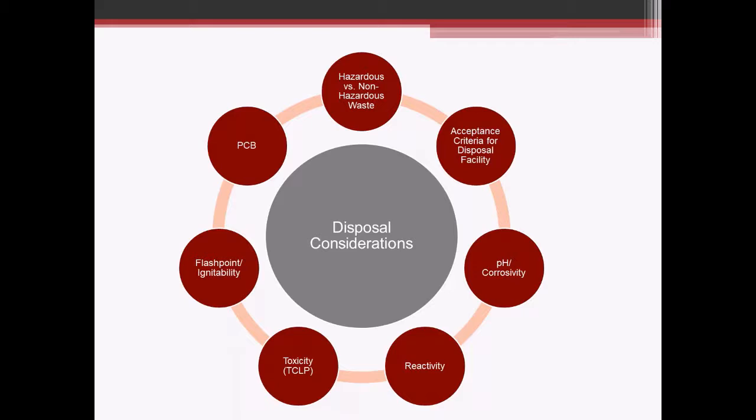On the disposal side, the main thing you're looking at is primarily: is a waste hazardous or non-hazardous? All types of waste need to go to a permitted disposal facility, but certain wastes that are considered hazardous need to go to landfills that can accept hazardous waste.